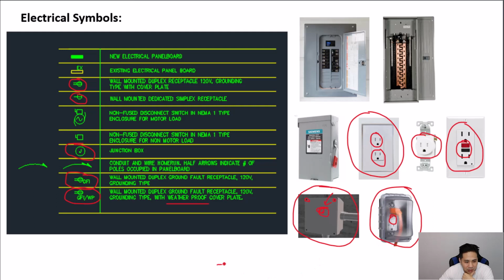Splicing just means that you have one end of a wire, and then you take another end of a wire, and you basically connect these two together using some sort of splice, which can be screwed on, or there are different ways. You can maybe crimp it on, which means you basically squeeze it together. And the splice basically connects the two segments of conductors.